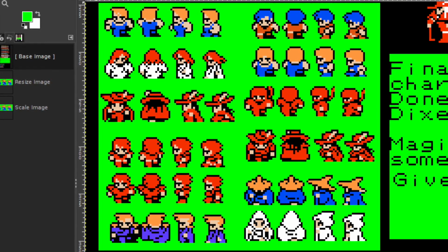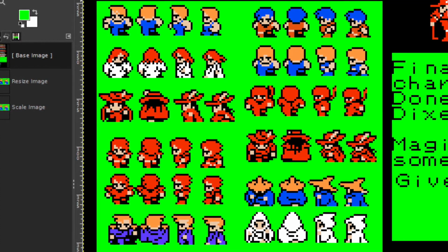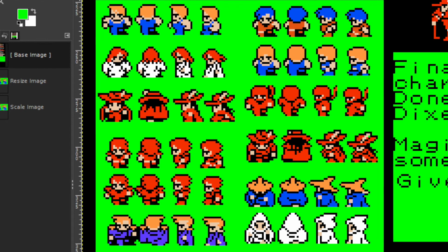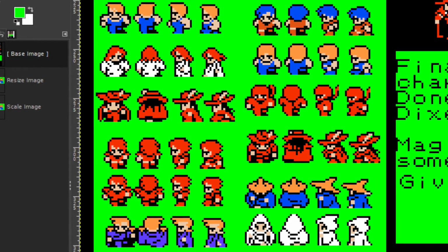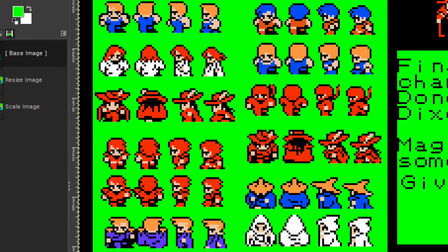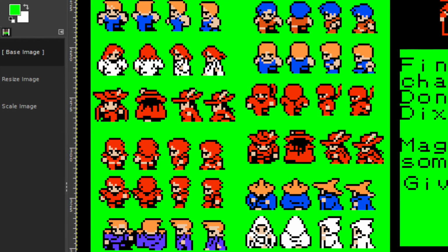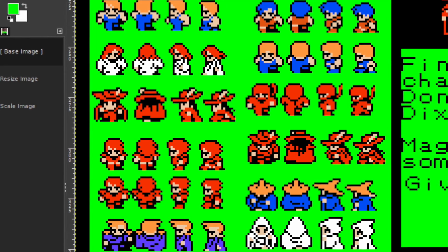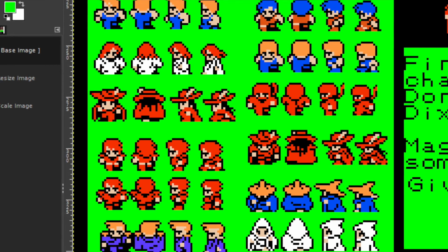Your animation will look best if you fill the 16 by 16 space with your character as much as possible. Otherwise, it can be hard to keep the character's position from shifting in unwanted ways during animation. Make certain your images are exactly 16 by 16 pixels in size. Otherwise, the converted arrays will give you too many/few initializers errors when you paste them into your Arduino code.